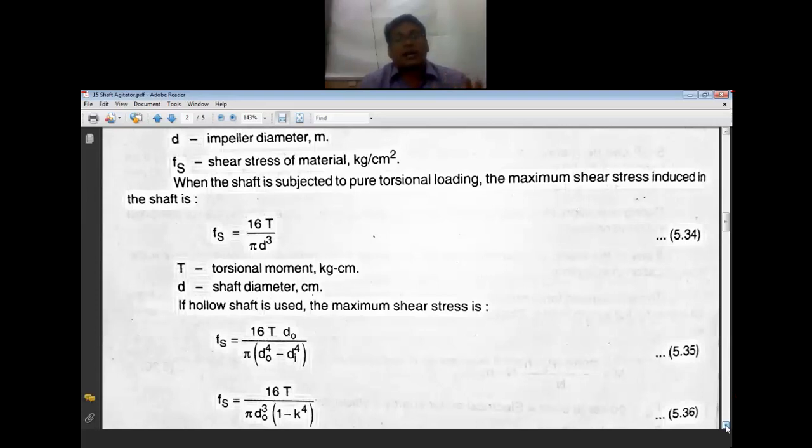Now the fan is rotating at a constant speed of, say, 3. So there is a continuous load that is exerted. This is load at a steady state. So load at a steady state and the fluctuating load have a difference. Fluctuating load is when we give a sudden jerk from 0 to 5. If I increase the speed from 2 to 3, then it will be considered a minor jerk, or minor shock, or light shock. And when it is constant at a speed of 2 or constant at a speed of 3, it is considered a steady load. So steady load, light shock and heavy shock, these are the 3 different situations.